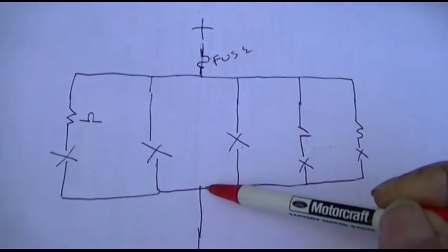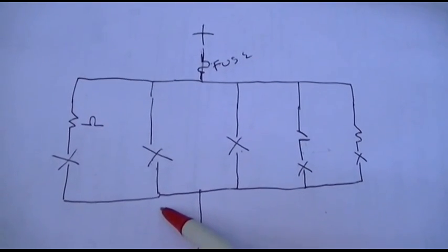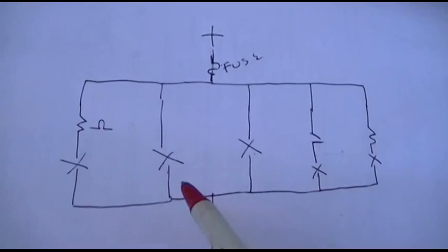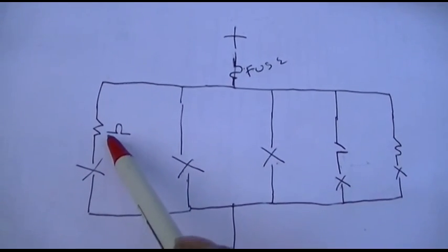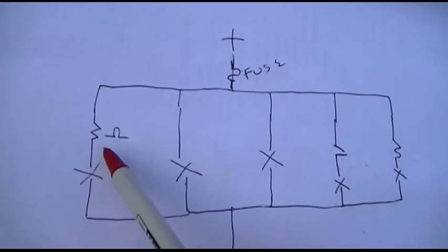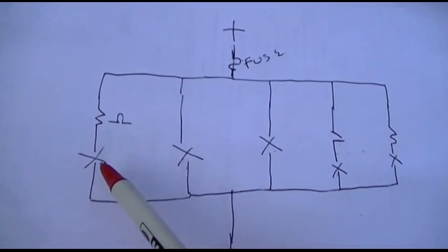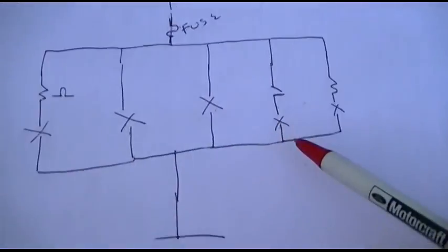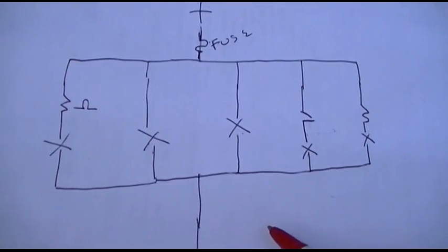That could definitely do it. Or maybe the audio output transformer could have a direct path to ground. But in general, you're going to have resistors for a lot of the low consumption parts of the radio, like the IF, the audio preamp. The audio amp might have a direct path, so you'd want to look at that. And in this radio, the final transmitter transistor might have a direct path.